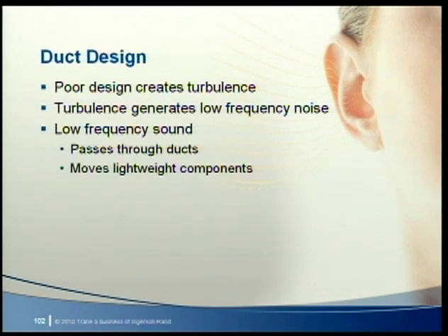This low-frequency sound is difficult to attenuate and may have sufficient energy to move lightweight building components and gypsum board walls. The resulting noise and vibration is difficult to correct. Attenuation is costly and in most cases ineffective. Often the only remedy is to remove the problem areas of ductwork by relocating the unit and rerouting the ducts.